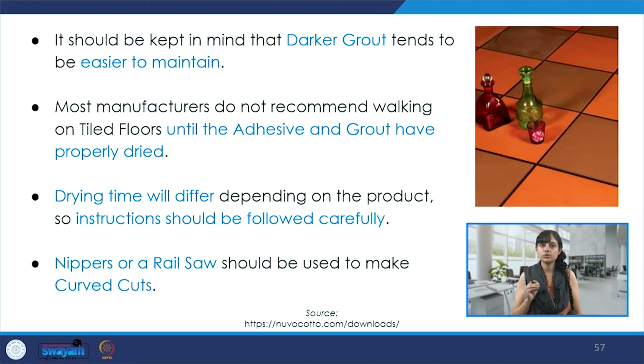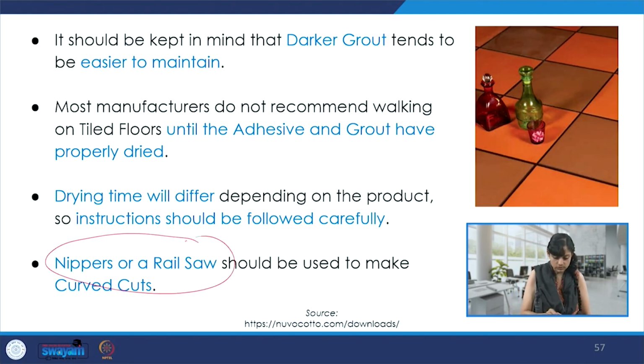Most manufacturers do not recommend walking on tile floors until the adhesive and grout have properly dried. So it's important that they are dried first. And the drying time will differ depending on the product, so it is very important to read the instructions. And then nippers or a rail saw should be used to make curved cuts. So it's not always the linear faces or just the straight cuts. It could be sometimes the curved cuts. So there are tools for that also.